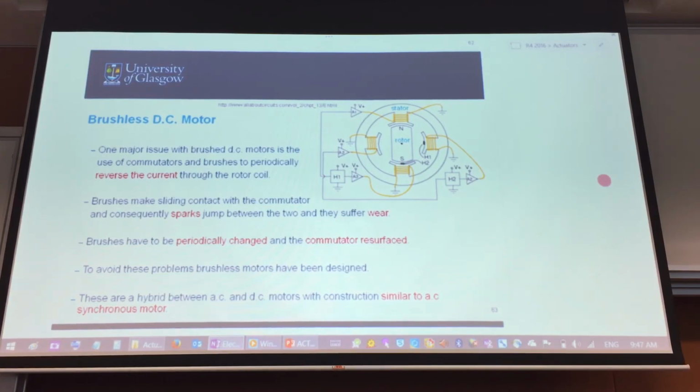That means internally, a brushed DC motor gets heated up without the ability to cool down. But in the brushless DC motor configuration, even if it gets heated up, the heat can be transferred out. The only thing stopping it is the metallic shell of your motor. So it can get transferred out, and hence you get cooled down.